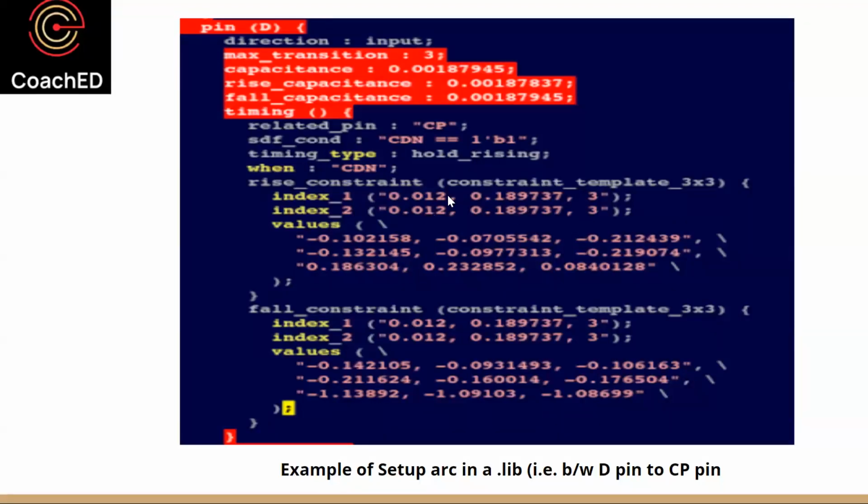Or a lot of times, if you are creating your own .lib, you can come up with your own combinations. The tool is just a simulation setup, but usually, in companies I worked in, there is an actual elaborate flow used to determine these numbers. It's based on which operating voltage the simulation is run at, what kind of cells there are, and what kind of threshold voltages the cells have, and based on that some of these values would change. But at your end, if you are running the simulation and trying to create a .lib, you are free to choose any combinations, as long as you don't have too many points.